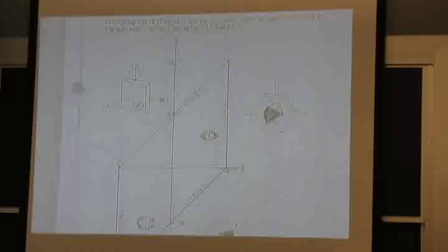So if I had a pure single crystal sheet with this texture, I would get a yield locus that looks like this, and I get this extra strength in this whole triangle up here above the Tresca would be cutting across here. All this extra is extra strength because I don't activate those extra slip systems because of the change in orientation of the crystal. Okay? So that's the 110 texture.